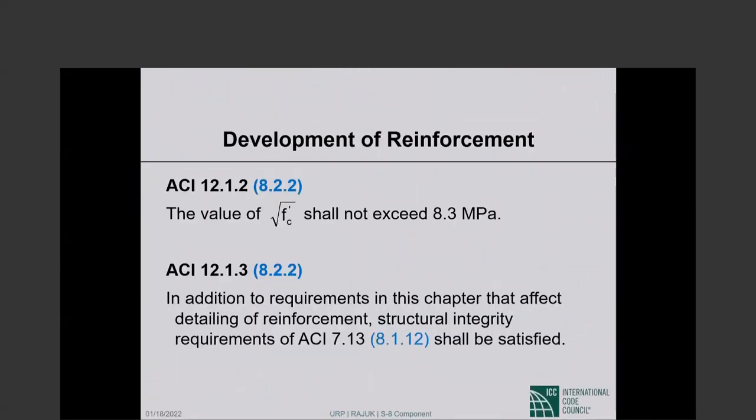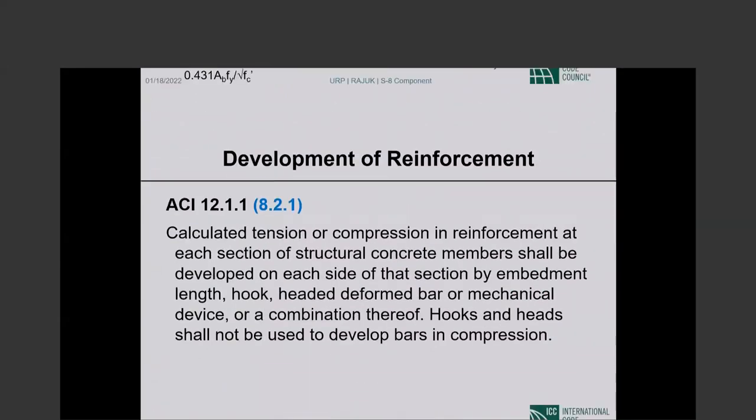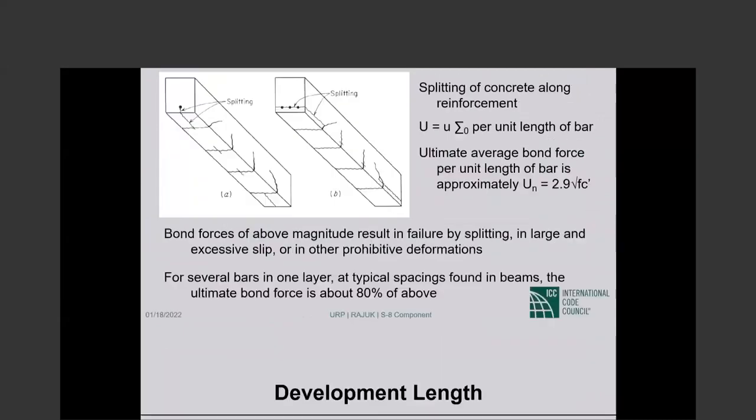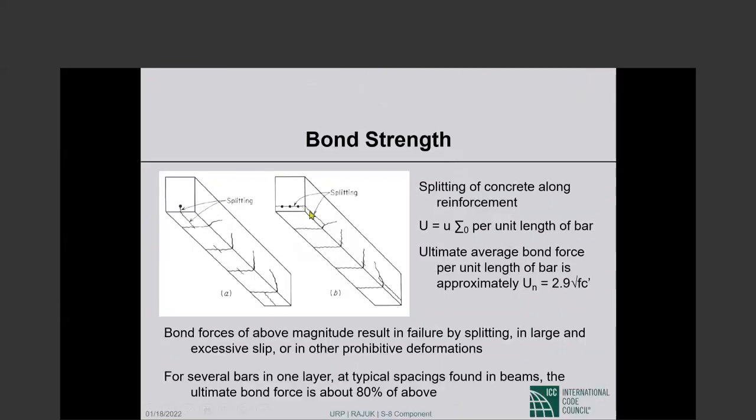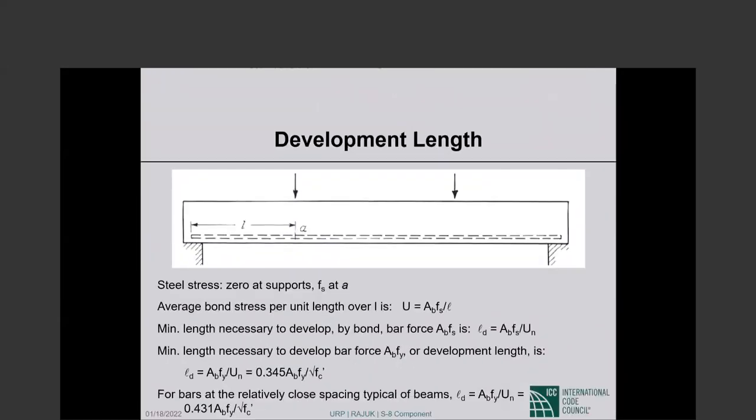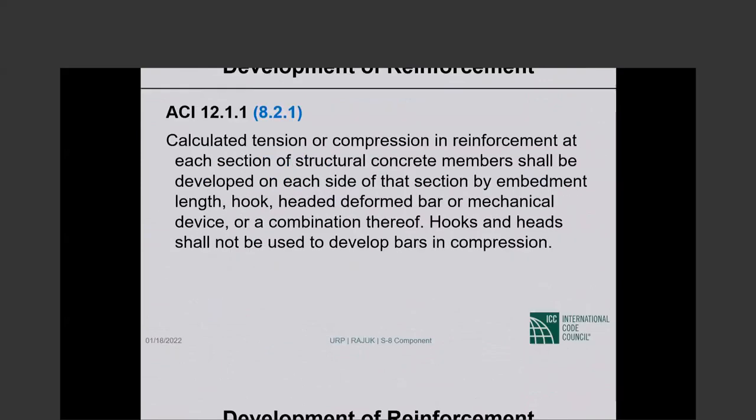You remember, it's some way to go back, but it may be worth it. So the potential plane of splitting: the transverse reinforcement that goes through all the legs of transverse reinforcement, total area within spacing S that crosses that plane of splitting. That's what we are saying here.